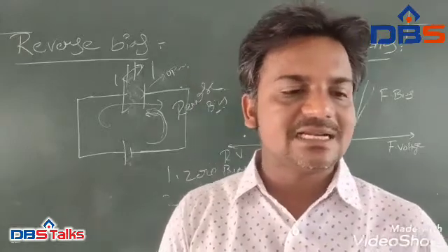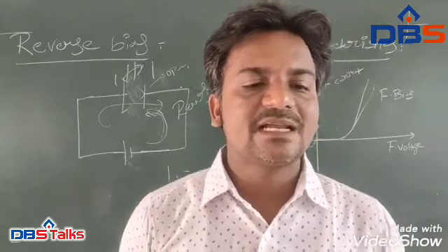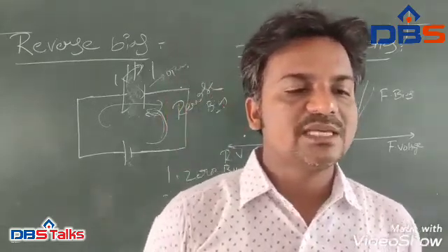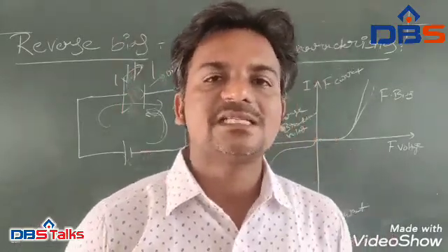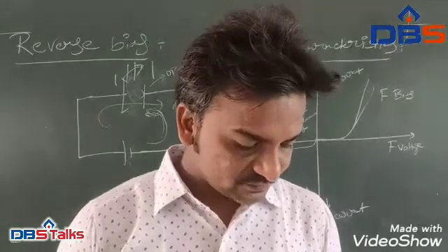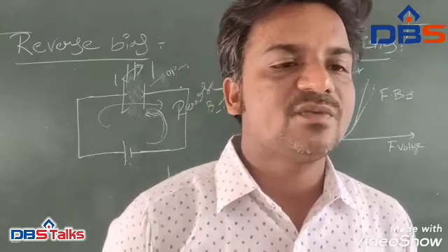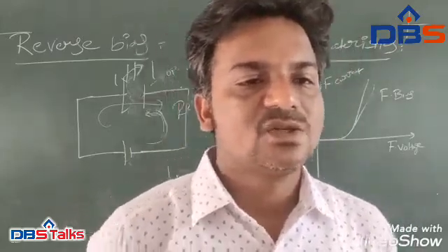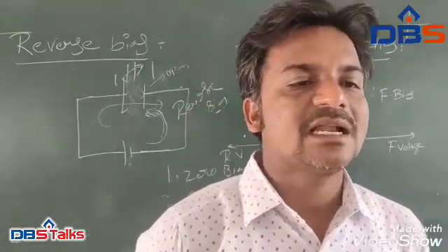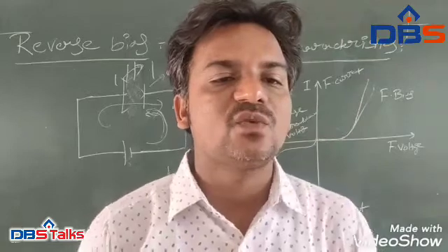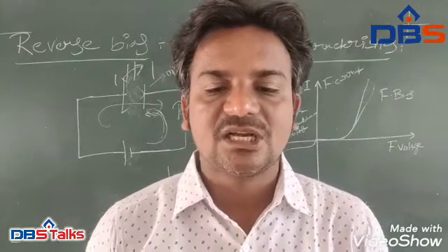So the result is that a high potential barrier is created, thus preventing current from flowing through the semiconductor material. So in this state, it doesn't allow any current. So this is also one type of equilibrium state. Due to this, there is an increase in the leakage current, but an electric current cannot flow since no circuit has been connected to the PN junction diode.